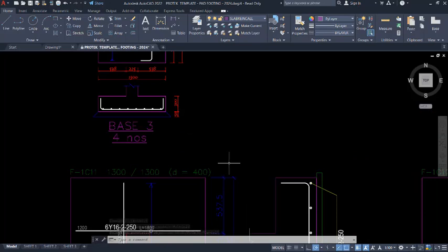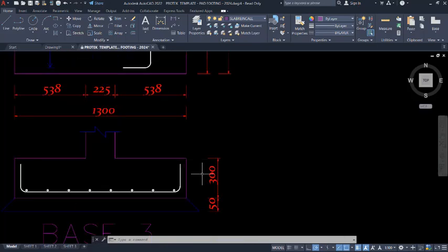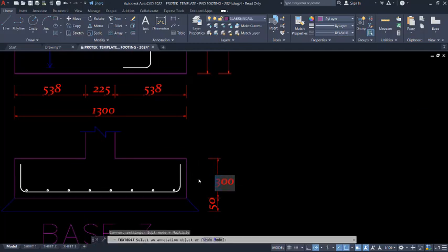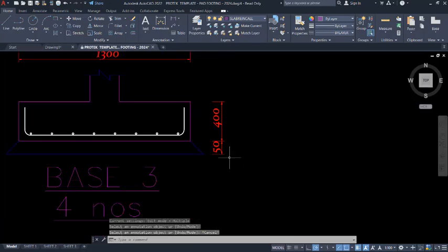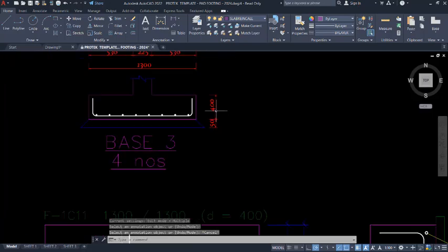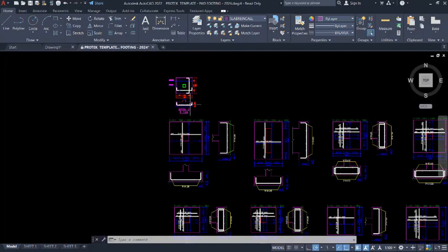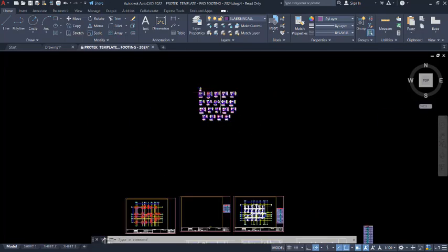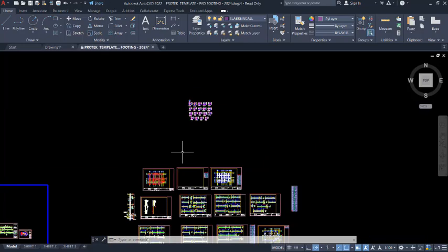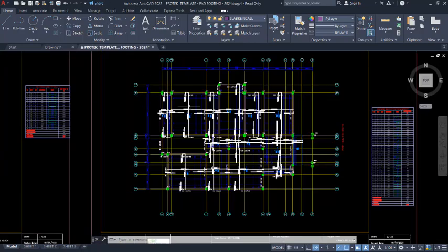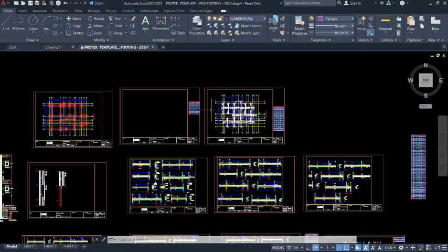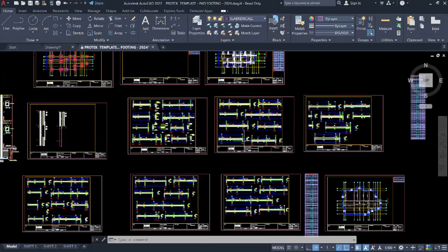Also check the footing depth here is 400. You can change it right here, depending on your design, to be 400. Then the blinding is always 50 millimeters thick plain concrete. Once you harmonize all of that, take all inside of your drawing. As I said earlier, on the slab aspects, we'll get the video on how you detail this in subsequent presentations.